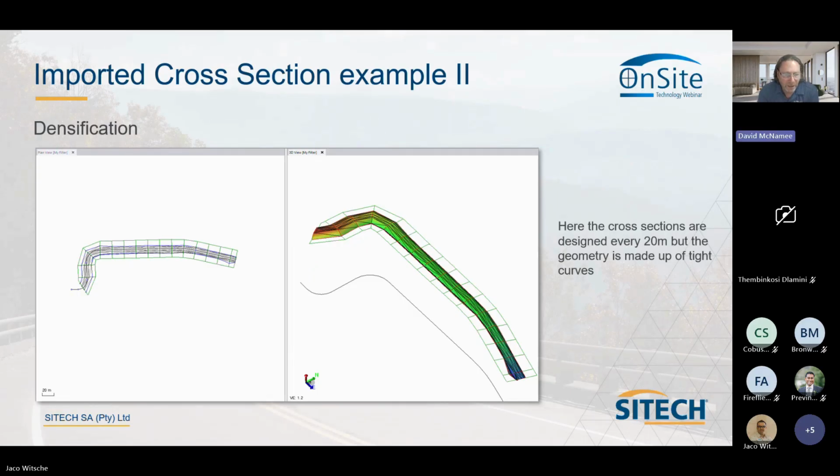You compare that curve to what the actual surface model looks like, you can see 20 meter straights doesn't look very good. Your accuracy is gone, your tolerance is outside of what you're trying to build. How can you build a model or a surface to 5 millimeters, 10 millimeters, when your design is automatically out by 60, 70, even 10 centimeters?